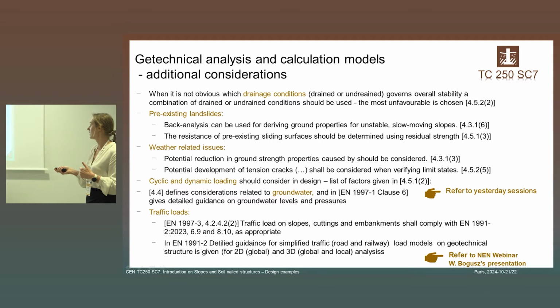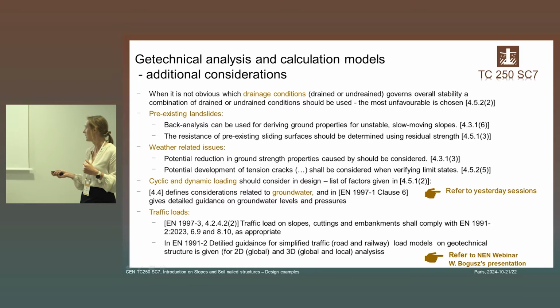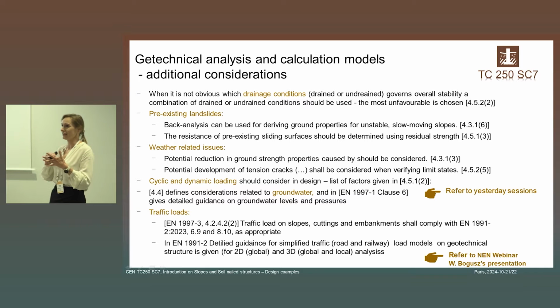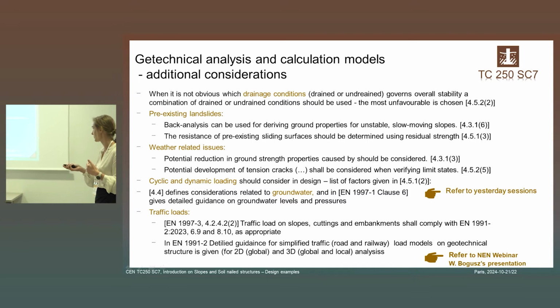And now in Eurocode 1 Part 2, there is detailed guidance for simplified models for geotechnical structures, for road and railway load. There is even the possibility of using a very simple distributed equivalent load. So very, very convenient.